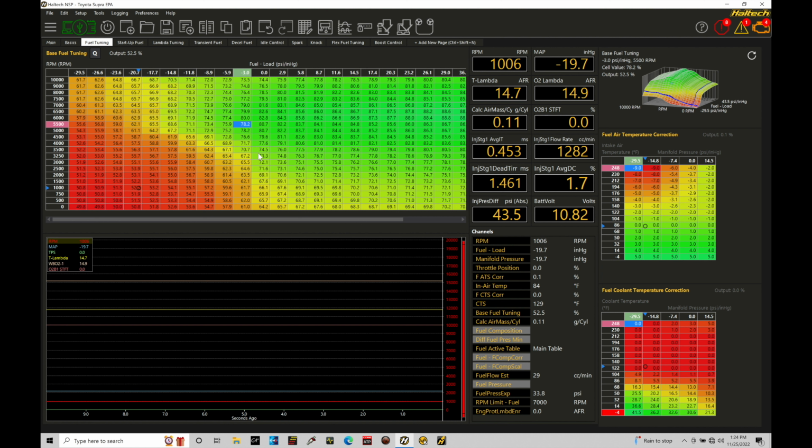We're doing this estimation based on knowing our MAP pressure, our volume per cylinder, which is displacement and number of cylinders, and also our air density, which is a factor of the air temp, charge temp reading. If we plug all that into the equation, and then also specify the VE percentage here, that's going to give us the actual airflow or air mass estimation, how much air mass is entering the engine.